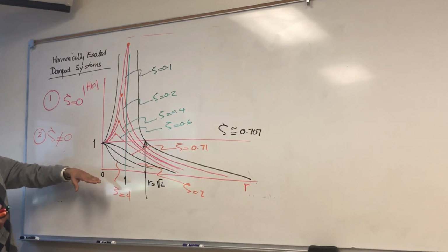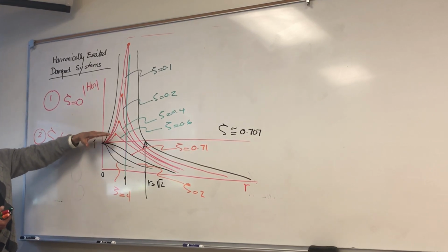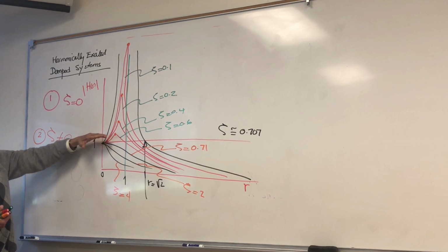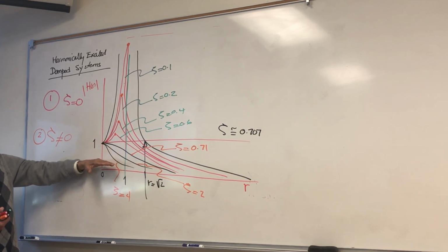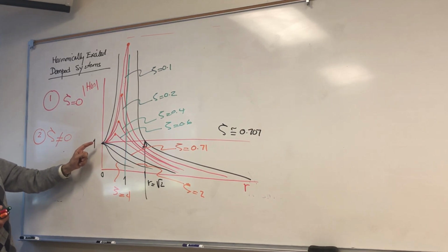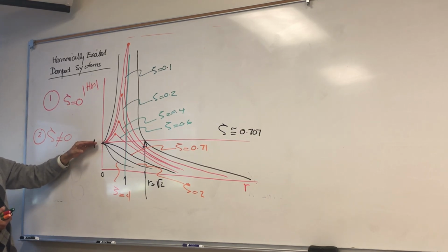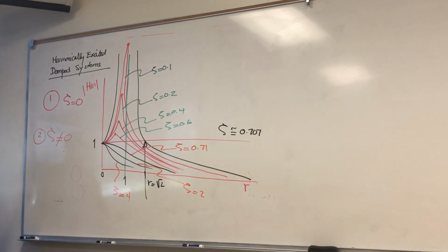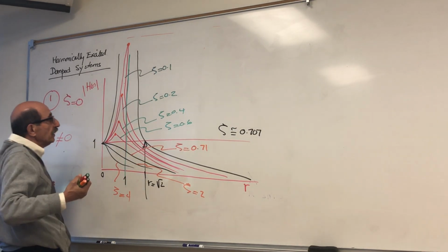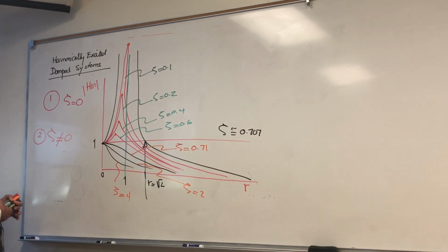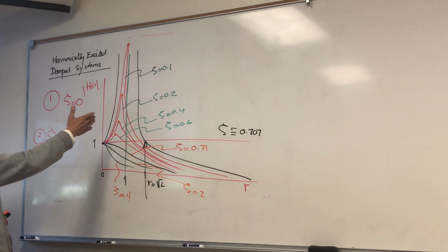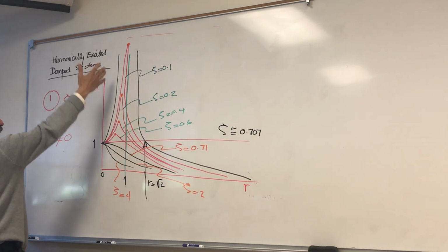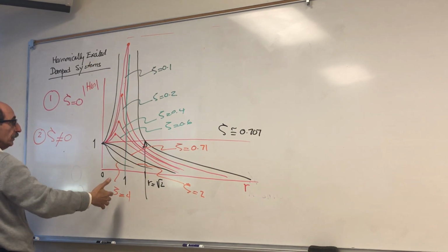You can see that, right? Below here, that means that the dynamic response is less than the corresponding static response, because this value, the maximum value, is always less than 1. So what is magic about this 0.707, or how did I figure out that this peak value, first of all, shifts to the left of 1, is never along 1.